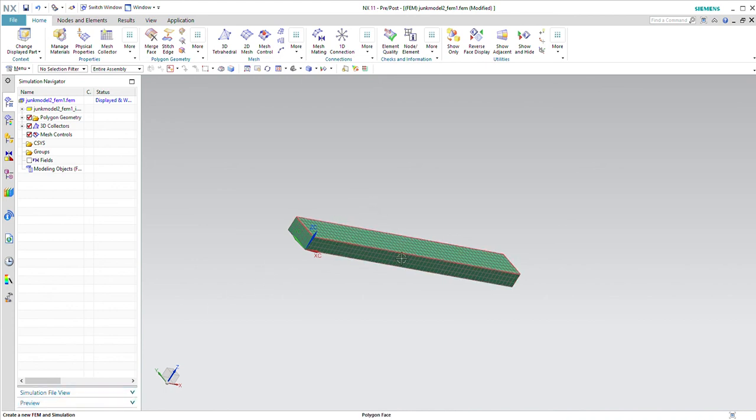It has a mesh. These two things are the things that you take care of in the FEM file. Now I need to go to the simulation file to create the load and the boundary conditions. I can either do that here, by clicking where I'm highlighting and right clicking, and it will say Display Simulation.